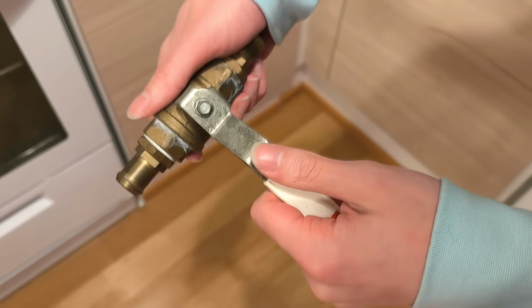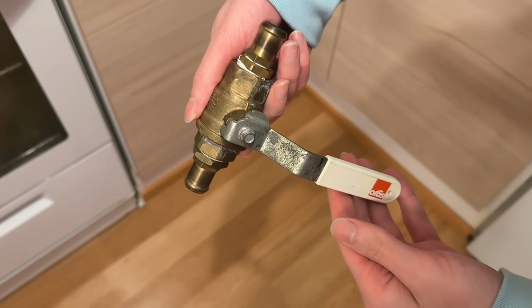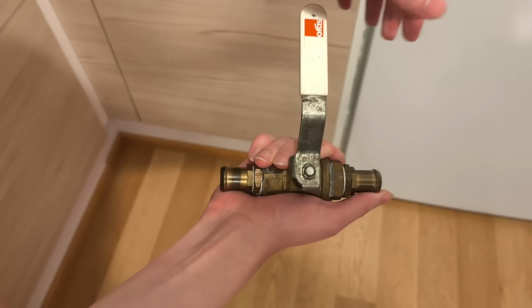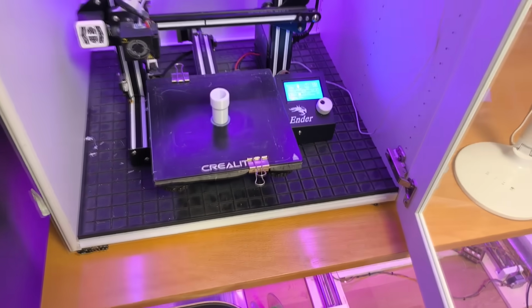I decided to use a manually operated ball valve because it's the cheapest, easiest to operate, well enough performing valve type. I estimated that the opening time for the valve is around 150 to 250 milliseconds, depending on how you open it, so it isn't the best in that regard, but it's good enough for what we're gonna use it for.